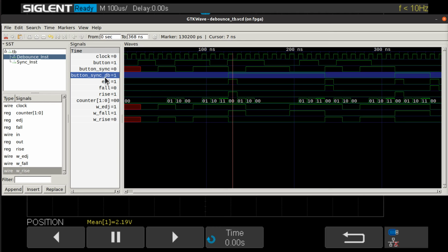If you start running out of FPGA resources because you've got a lot going on, a lot of buttons and a lot of circuitry, that's the sort of thing you need to start thinking of. Now, let's get a little bit more advanced from where we're at right now in this series, but I just want to plant that seed because it can come back to bite us, and you don't want to get all upset that you got 7,000 LUTs and they're all burned up in your stupid key debouncers.